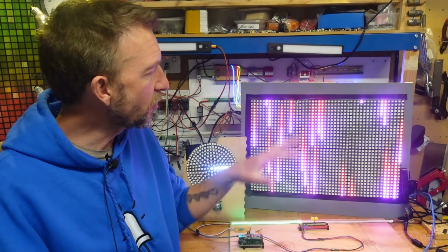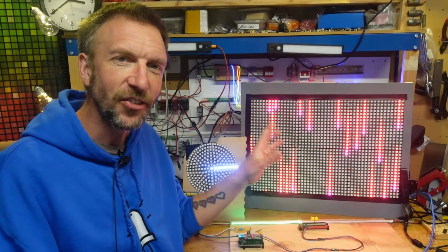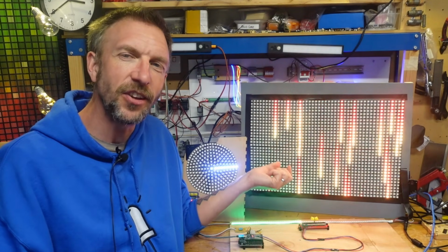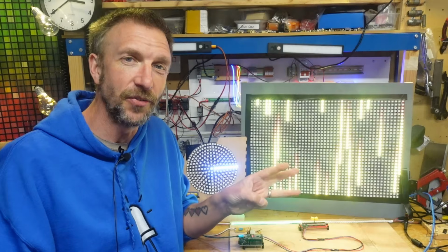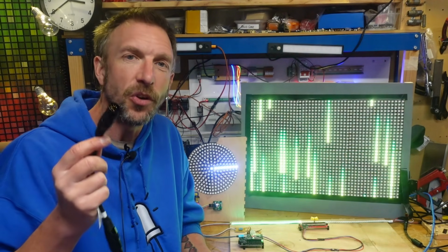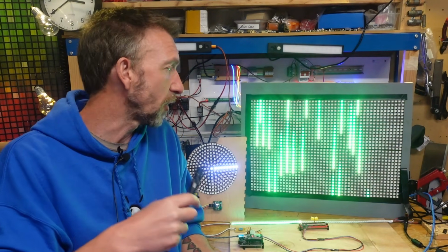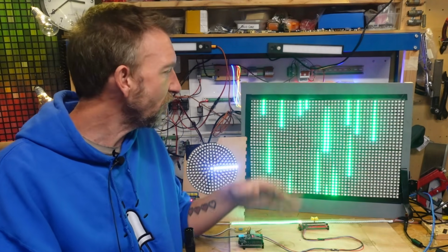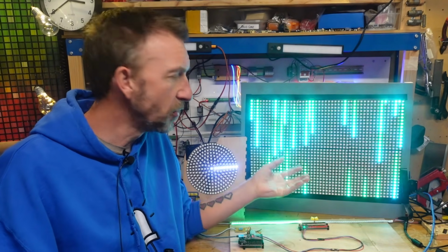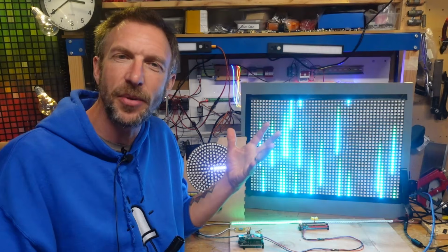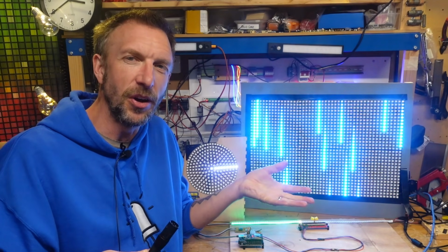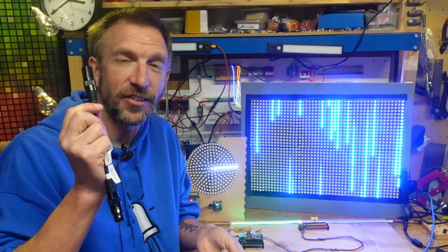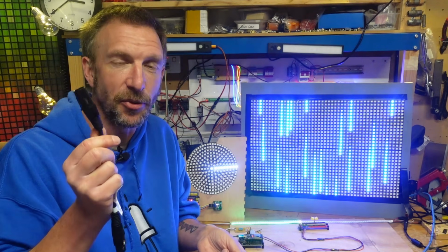But when it comes to controlling LEDs, each LED has a red, a green and a blue intensity value. So that's 3 channels of data. And that means that one DMX universe can only control a maximum of 170 LEDs. And because LEDs are typically quite small, high density fixtures, that might only get you a couple of meters worth of lighting effects. And you can't send more than that down a single DMX cable.